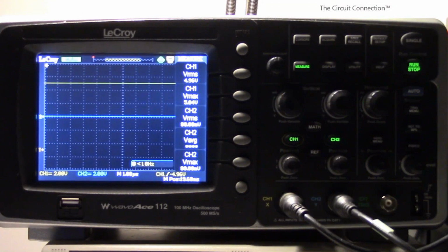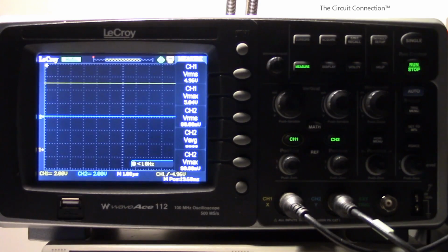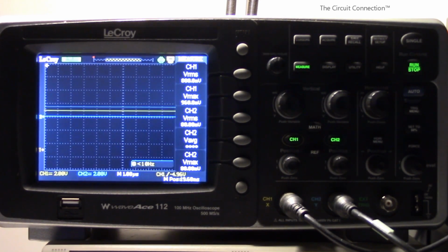Okay, I am going to do a very short demonstration here for a TTL inverter, and that TTL inverter is the 74LS04. I'm going to trace a curve, so basically I'm going to be doing a DC sweep with it and get the voltage transfer characteristic out of it. So if I reduce my voltage, we'll see at some point this will go high. Okay, so around there. It may exhibit some hysteresis, but maybe not. This is in a YT format, and I'm just doing this to see what happens and what I can expect.